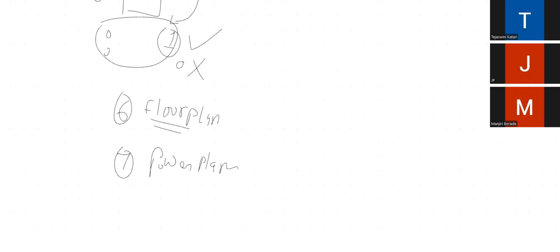Similar way, for standard cells, even though we are not placing them, we are creating the power plan, and the goal of the power plan is to distribute the power uniformly. So even if the standard cell is placed in a corner or the middle, it should get ideally similar power. That's why standard cell information is not required. So that is the power plan.